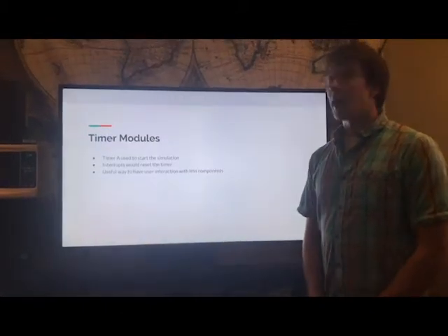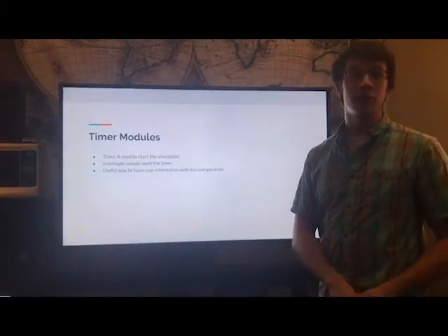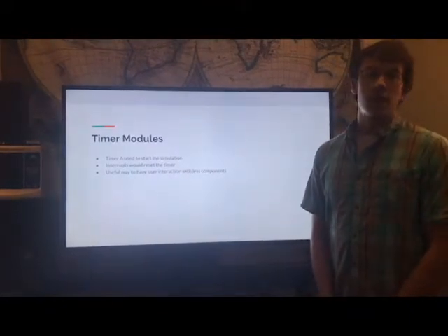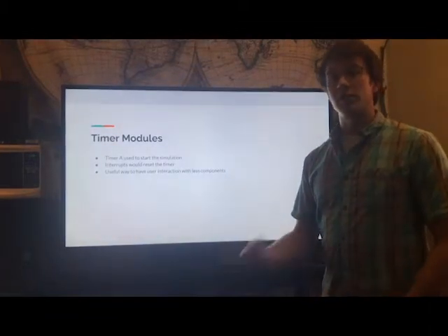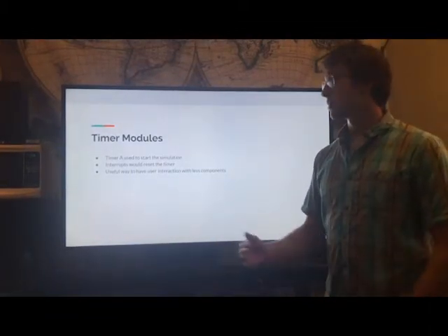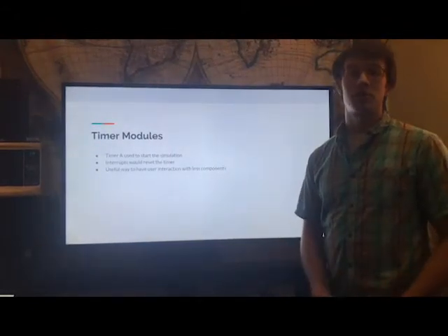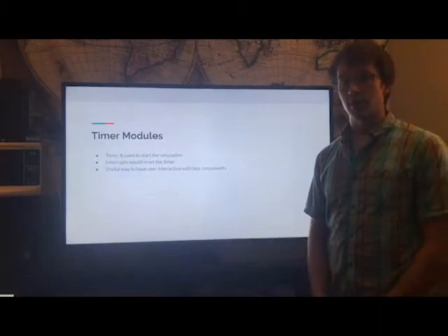We use an idle period, so a certain amount of time since when the user has last pressed a button, as the way to start the simulation. We used timer A to keep track of this, so every time a button was pressed, it would reset timer A, and then timer A would decrement, and there would be a check whenever it would hit the interrupt that if it got below a certain threshold, it meant to leave the control flow and enter the simulation itself.